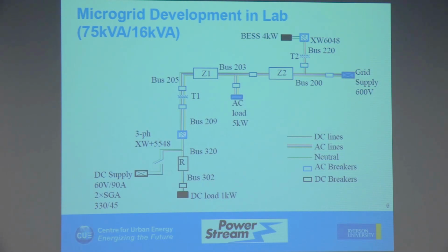One of the limitations is that if I put a large generator on one phase, this cannot act as a load for that particular phase while becoming a generator for the other two phases. That is a limitation. So we have to make sure that there is net positive demand on all the three phases, by nature of the converter design. So during that time, whatever the demand on the network, it is going to be met by this DC source. So what we deem is that this DC source is the infinite bus, right?